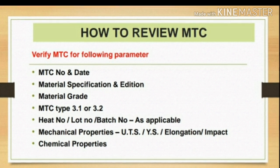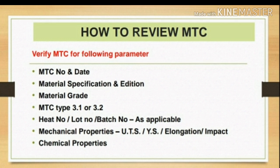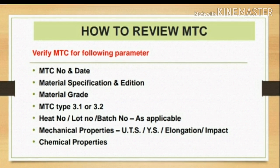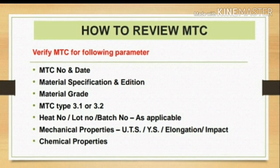Every raw material should be received with material test report. It has to be with material test certificate because all the traceability is mentioned on the material test certificate. All parameters are mentioned. So QC engineer's job is to review this MTC in compliance with the material specification and the actual material received. So I will be summarizing few checkpoints how we can review the material test report. So there are few points based on that QC engineer can review this MTC.